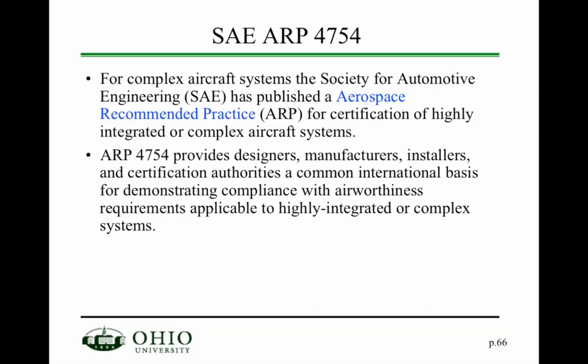Now, if you look at complex aircraft systems, nowadays a lot of aircraft systems are complex because they have both a very advanced hardware component as well as a very advanced or big software component. So what the Society of Automotive Engineers, SAE, has published is what they call Aerospace Recommended Practice, or ARP, for the certification of highly integrated or complex aircraft systems, for boxes that have both hardware and software.